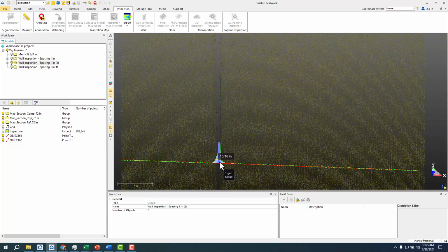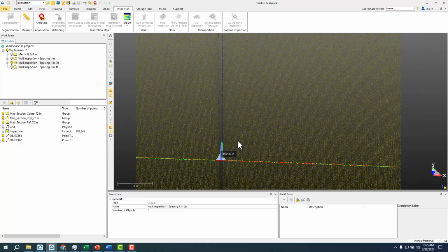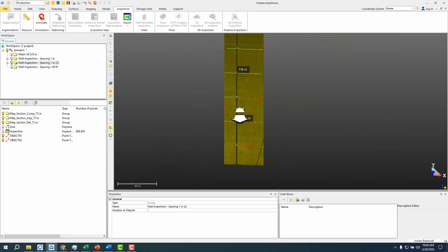And then I could go and add in some more specific measurements if I wanted to communicate where it is. Export them as a DXF. They'll come into CAD or Revit in the right location, because you should georeference your scan data to that model before, so everyone knows what we're looking at as far as the issues we're seeing.